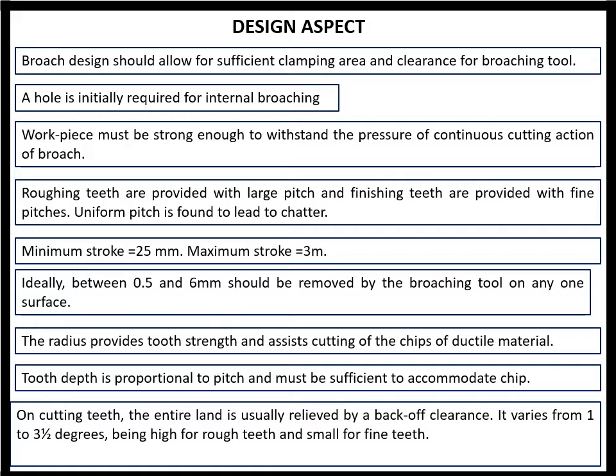So ideally the total depth of cut, the material to be removed from these surfaces, should be kept in a range between 0.5 to 6 millimeter, so that the material is removed by all the teeth in one go.